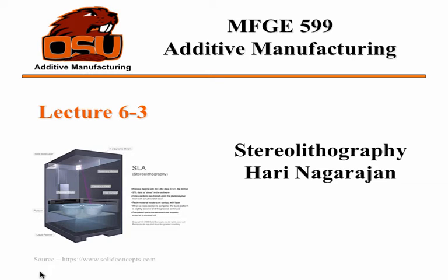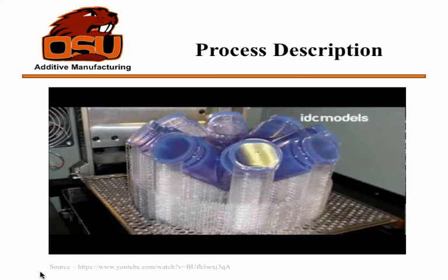I'm just going to continue about stereolithography and the basic process and part parameters, which differ the part quality based on both part accuracy, as in dimensional form factors and surface roughness, and at the same time part strength, as in tensile strength and all that. So just going to start with the video.